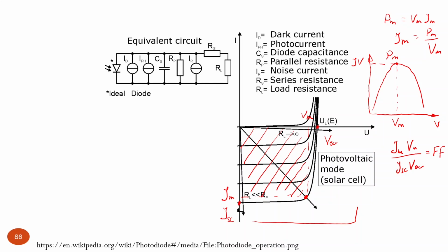Can I ask, in this problem we have plotted power against voltage, PV. We have the curve having this parabolic shape, like the curve is upside down. I mean, that's because you took negative current. But power cannot be negative, so by definition you take the absolute value of this, so it will be flipped over. You cannot have negative power, it's not fighting against thermodynamics. Since you have negative current, because photocurrent is in the same direction as reverse current, as we discussed previous time. It's negative because reverse current is negative, but power cannot be negative, so we take the absolute value.